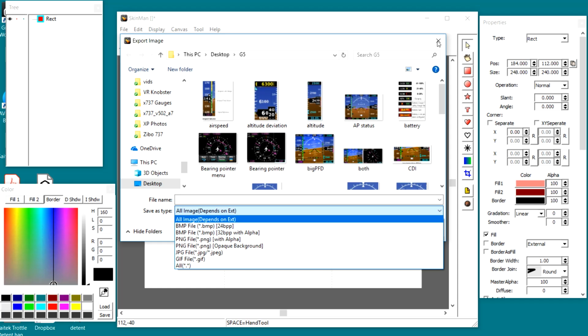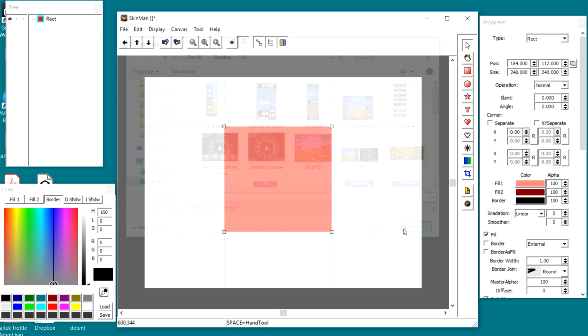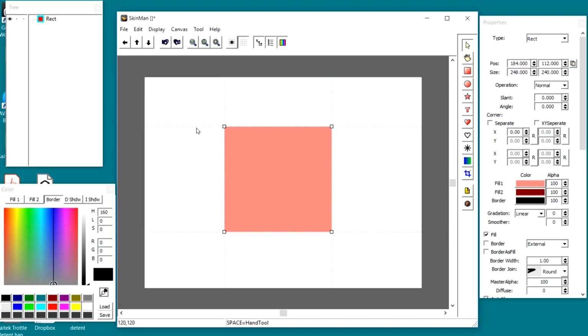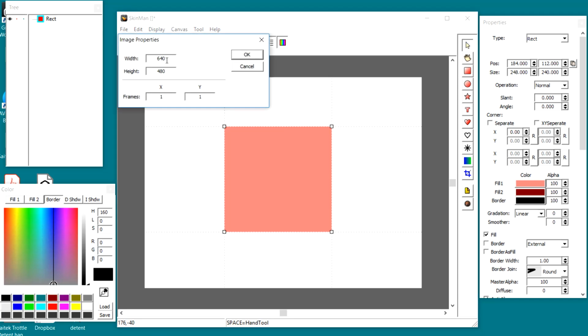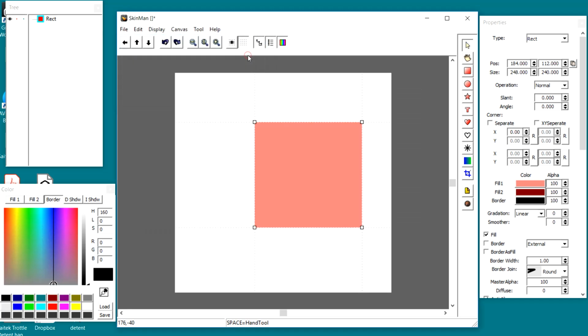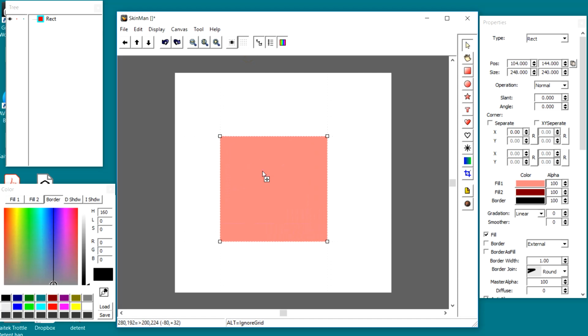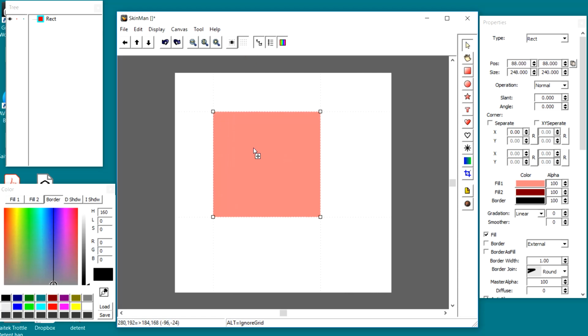Any area, even though there's a white background there or whatever color you select, if you select alpha, the background doesn't go with it. So what it would look like if we exported this as a PNG with alpha would be a big clear area with the bounds of this square and this pink area in the middle. Now, as I said yesterday, with the image you can set the size. Let's just set this for something reasonable to work on an instrument. Say 500 by 500, assuming we're going to make a square instrument, and we'll say OK. And you can see that we have the object here.